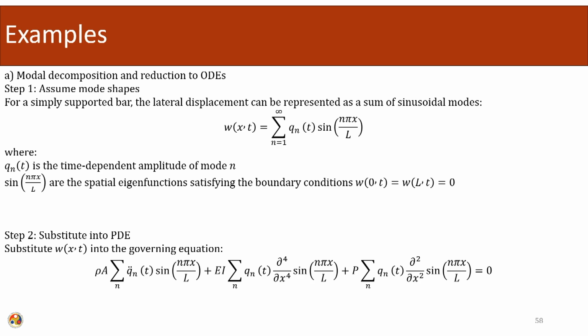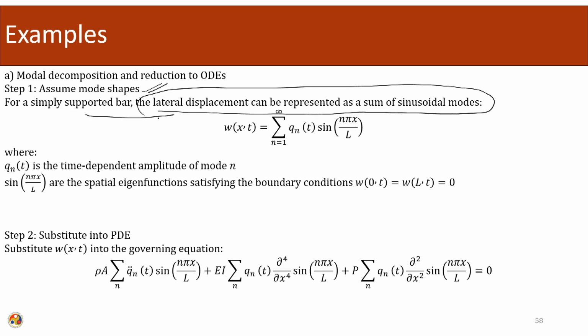The first part is the modal decomposition and reduction to ordinary differential equations. First, we assume the mode shapes. For a simply supported bar, the lateral displacement can be represented as the sum of the sinusoidal modes. Basically, the system will be vibrating in a combination of all the modes, and we are trying to separate out each mode.